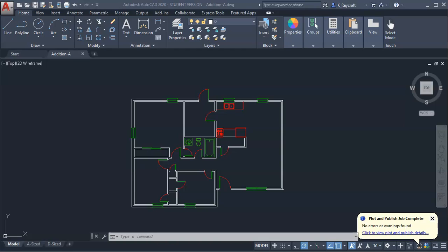Okay, we're going to talk about external referencing. We're going to run into situations where we want to bring in multiple drawings together without using the insert block command. When you bring in or combine drawings together using insert block, you're making the drawings larger by compounding the amount of geometry that makes up that drawing.